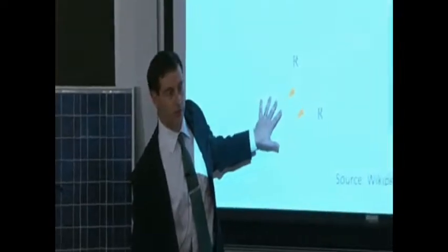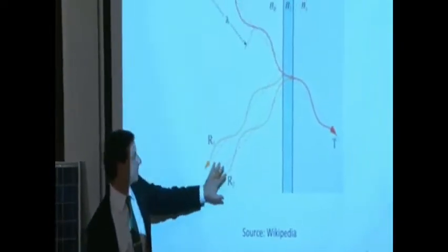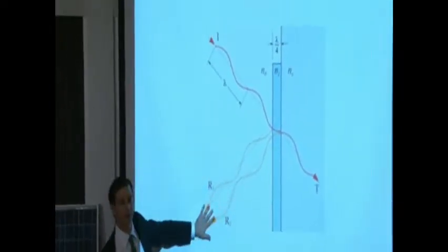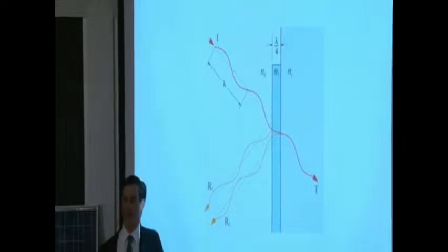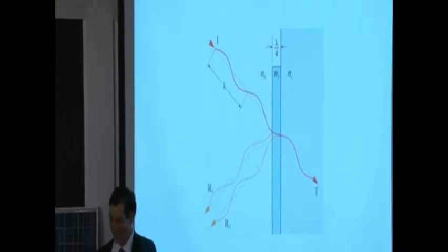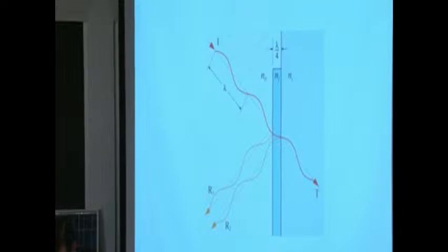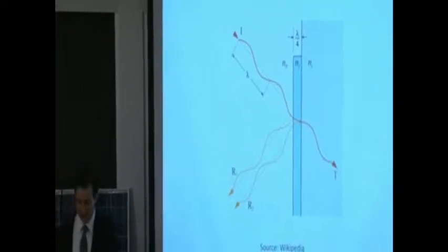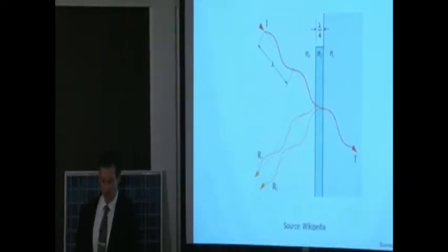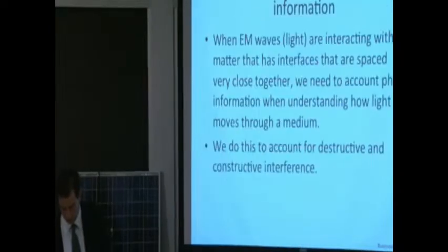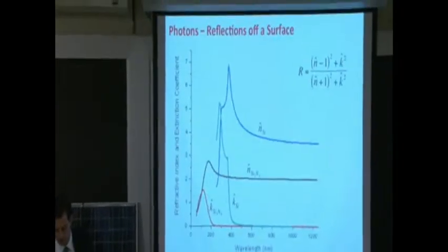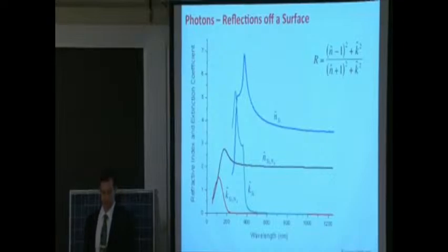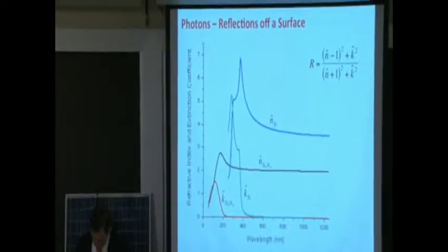The anti-reflection coating is enabling the light to be absorbed because it's suppressing the reflectance. The reflected modes at that particular wavelength are suppressed because of the destructive interference. That's cool. I really get a kick out of anti-reflective coatings. So they're 70 nanometers thick, and you gain quite a lot in terms of cell performance. I'll show you some slides to drive that point home in a bit.